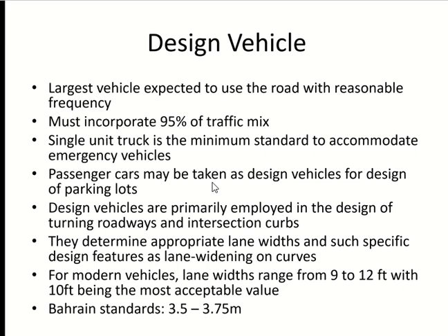No. It should go directly to the front gate. So you need a direct access road to the front gate. You will not design the parking lot for the emergency vehicle. You will design a road which will come from the main road directly to the gate for the emergency vehicle. Got my point?